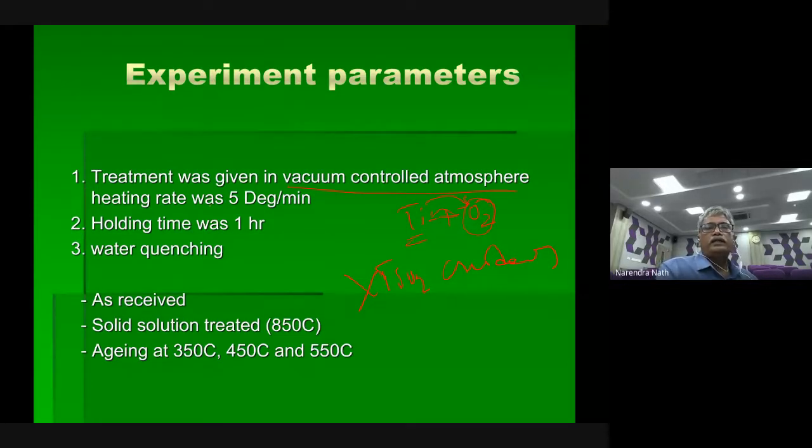And heating rate, one has to think, because when you use your furnace, very fast heating, say 15 degrees centigrade per minute, 20 degrees centigrade per minute, damages the matrix. So better to go with a lower heating rate. That means uniform temperature distribution, and at the same time you are allowing more time to react with the neighboring element and make a uniform structure.